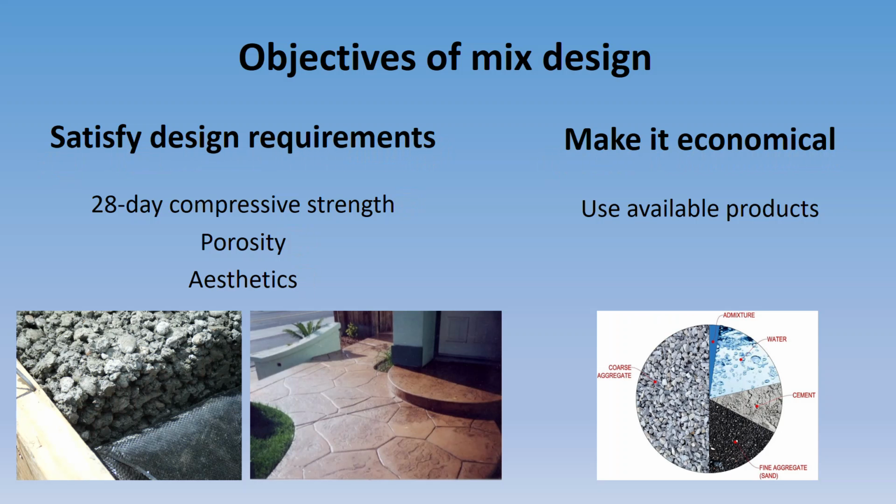Montana was really hesitant to adopt porous concrete. There's been a couple really, really good projects that have been studied in Billings and also in Helena, and they're proving to hold up really, really well in this climate. They're working wonderfully. You do have to run kind of a vacuum over these things every couple years to vacuum out the sand and the silt that builds up and gain that porosity back. But anymore, that's becoming a very important property of concrete that people are writing into the specifications.